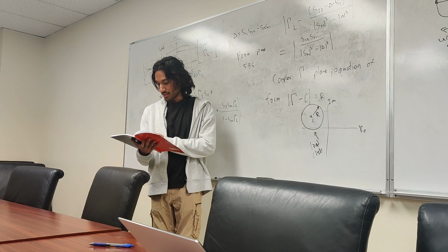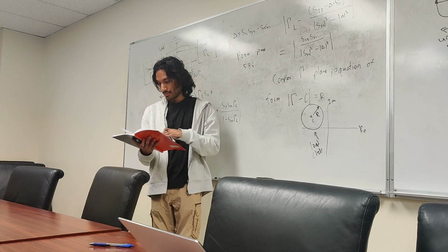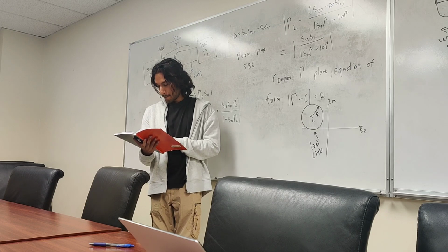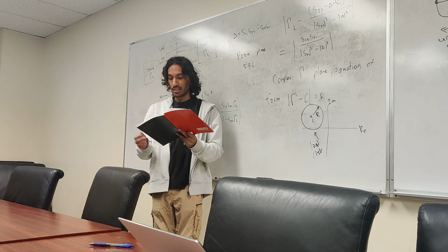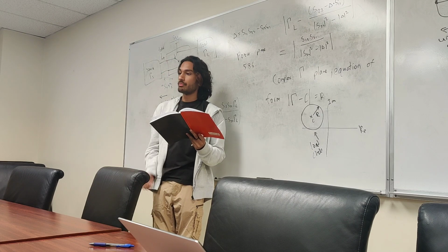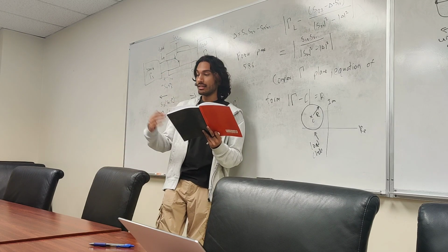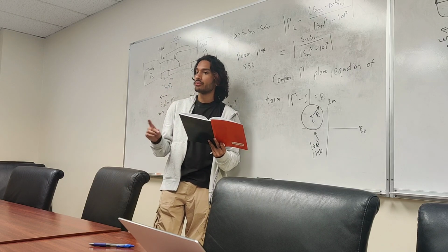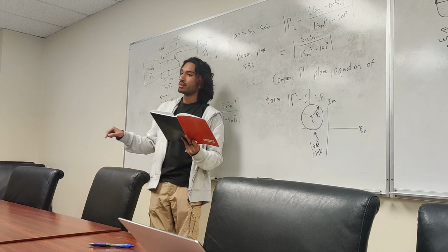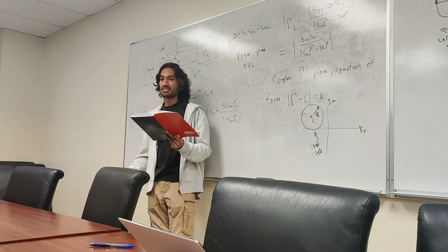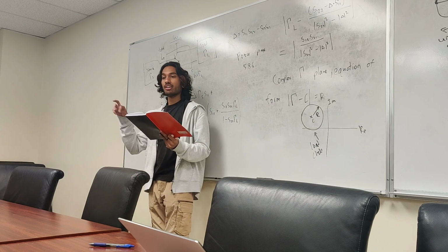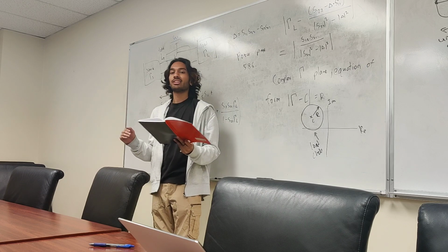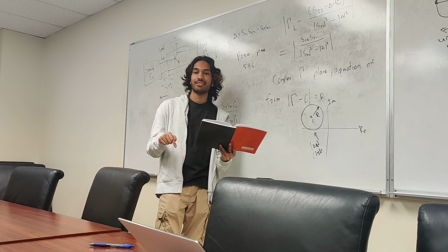It turns out that, I don't think I mentioned this explicitly, there's an example in the book as well. But S21 squared is not the highest point of that transducer function. This is kind of weird because that transducer function simplified itself to S21 squared when we were matched. This means that there is a point at which we are unmatched that gives us the highest gain possible. That's a bit weird to think about. We would expect highest gain when we are matched.